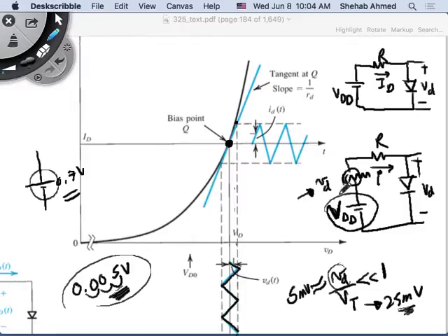Now VD brought you to this operating point that we figured out how to calculate iteratively and graphically. Now the small vd is doing what? Small changes around the operating point. Actually, it's called the DC operating point, or the DC bias point. Remember the bias currents into the op-amp? This is exactly something similar to that. We will talk about it, the transistors will have something similar.